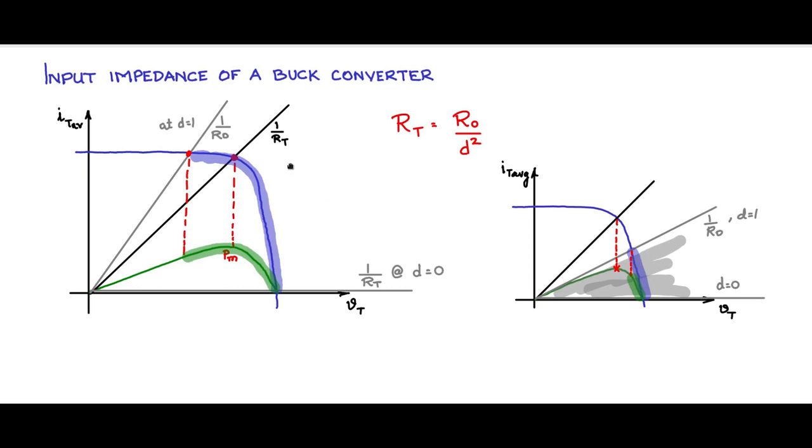You should, for the buck converter, have a scenario like this where the extreme 1 by R0 slope line, that is the load line slope, is such that the range of operating points should allow for a possibility of peak power point operation, so that the peak power can be drawn from the PV panel, which means the peak power operating point should be a reachable point for the buck converter zone of operation.